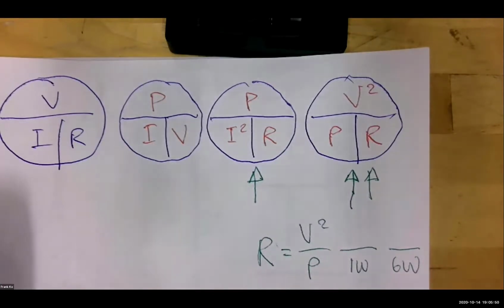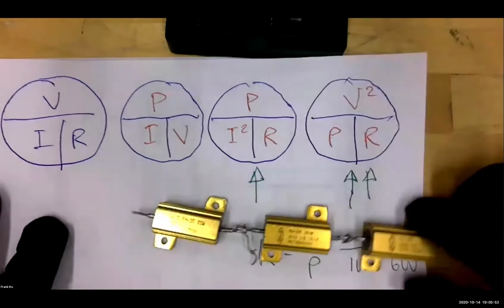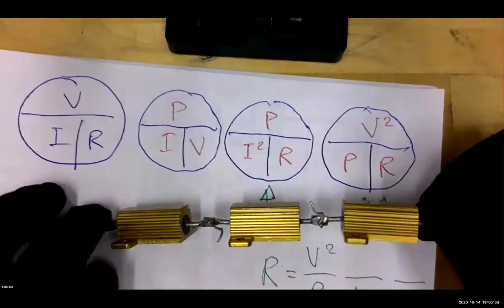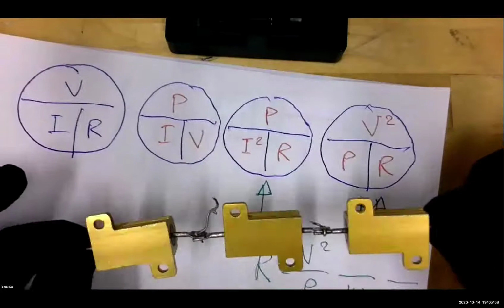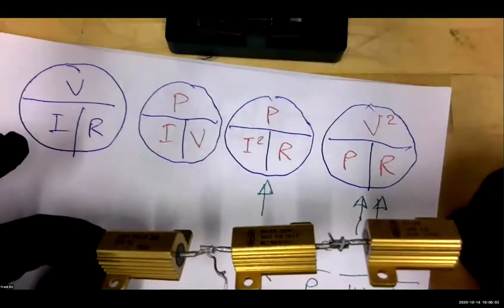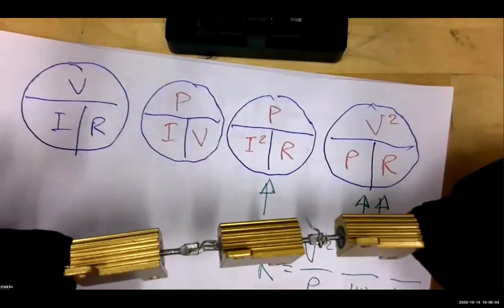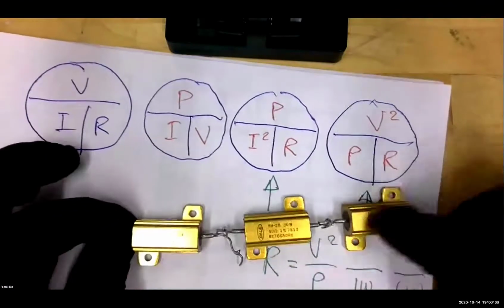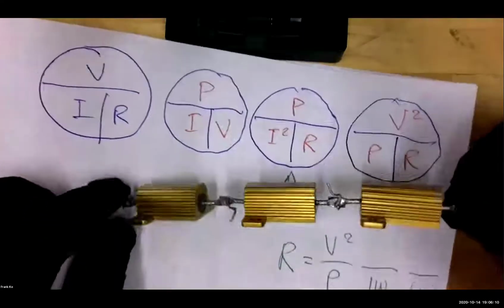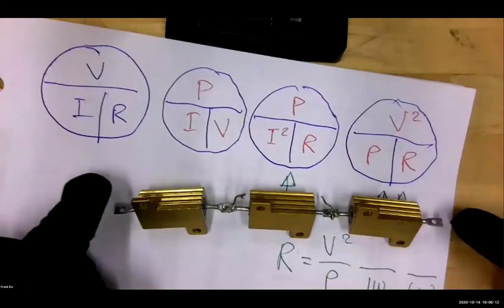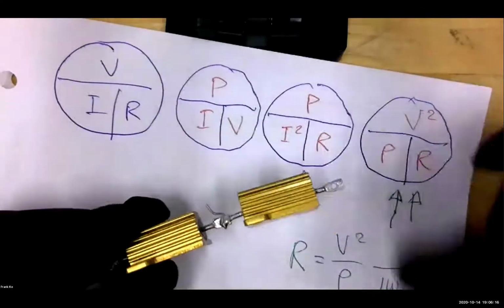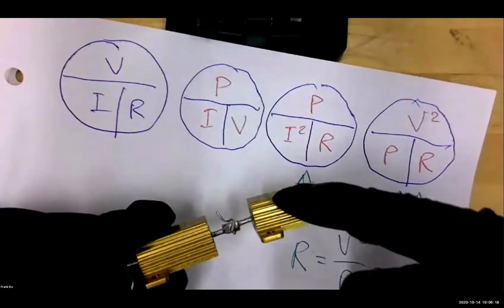And what they look like is something like this. Okay, these are high wattage resistors. Now, for the ohms that I calculated, this particular set of 3 worked out properly. This ohms plus this ohms plus this ohms worked out to give me the total ohms that was pretty close to my calculations. All right, but these are high wattage resistors by virtue of the fins.